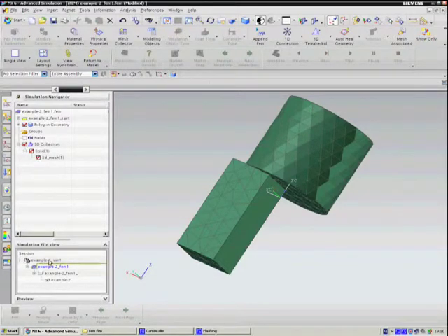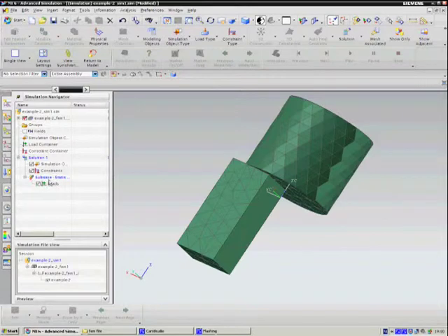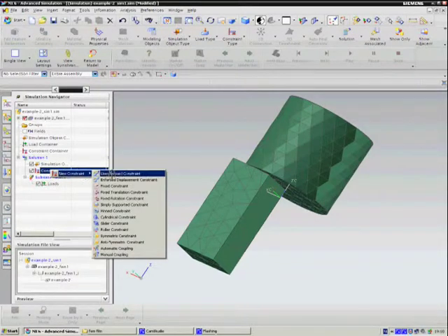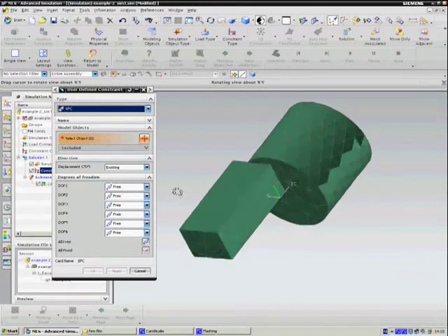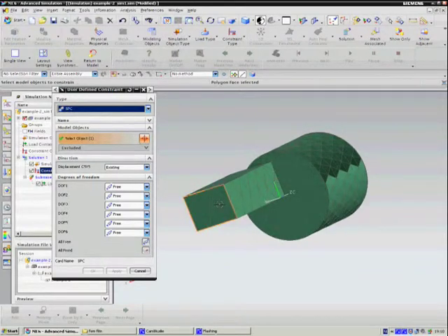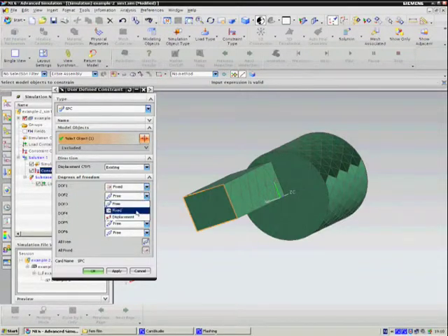After the material is applied, we go to the simulation file or sim file and we add our constraints. We want to clamp the bottom of our model with a user-defined constraint. In a user-defined constraint for 6 degrees of freedom, from degree of freedom 1 to 6, you have the ability to specify what is allowed and what is not.